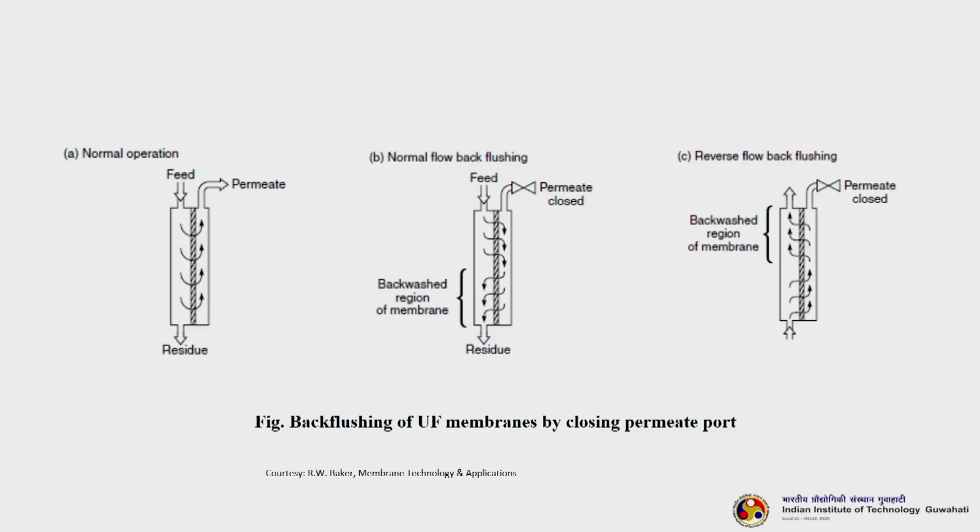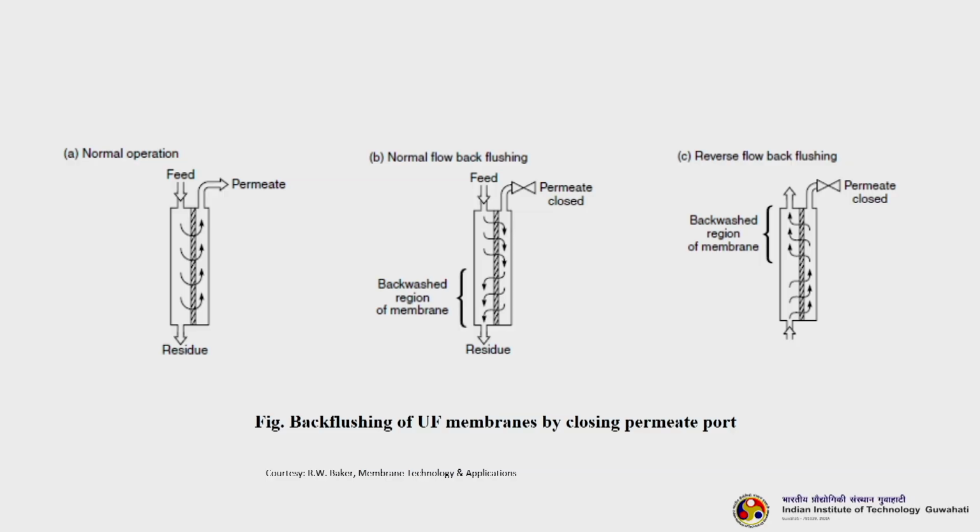So, and then again go for the repetition of the cycles. After successive cycles, when you see your permeate flux performance is good, or you are getting a good permeate flux, then again you stop this process and rinse it with fresh water a few times till you get your desired flux, right.